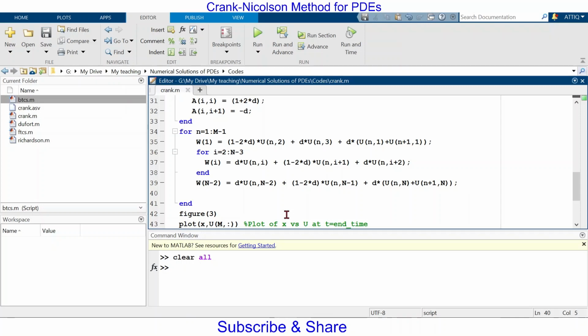Now, if we are using MATLAB built-in solver, the next step is very simple. Let's say we call the unknown as z. So we will just do a backslash w. It will solve this system of linear equations. But the computational cost will be greater in this case, and we will deal with it later in this video.